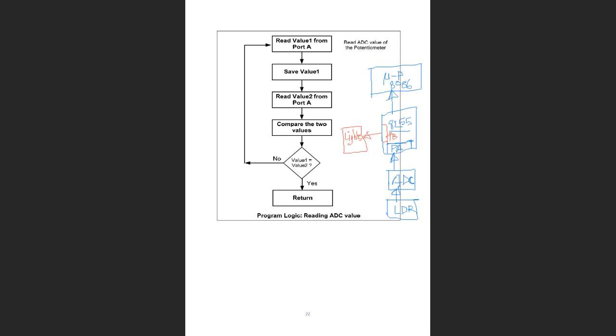All right. So that means here, port A is an input port and port B is an output port. Port A is here to take the input data of the LDR, the light brightness data, and port B is used to turn the lights on or off. Like in our trainer board, it will be LEDs. We consider it as a light on a small scale, just like the 8 LEDs in our trainer board. You already know it. Think about them as 8 lights in a room.